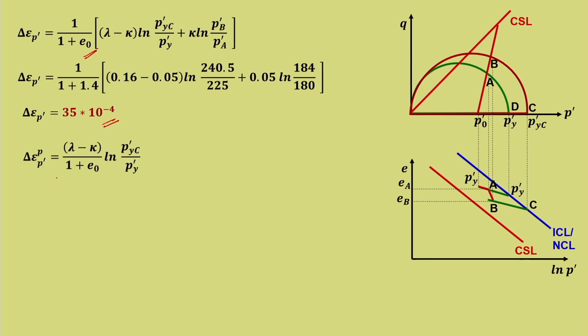Now, we need to find out the Q component, that is epsilon Q. What is the epsilon Q when it moves? So, both elastic as well as plastic we need to understand. So, epsilon P dash P is equal to lambda minus K upon 1 plus E naught, that is the plastic part of this volumetric strain.